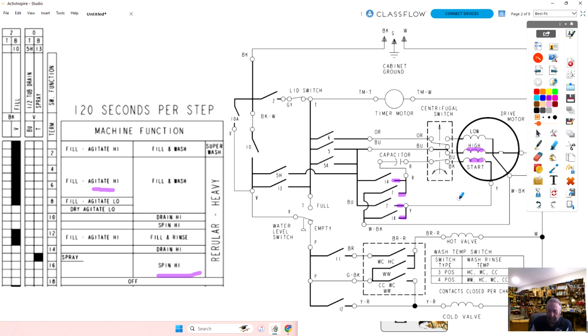What part do you replace? The motor itself? No, no, the timer. Let's do this real quick. It's not advancing. Is that why? No, look, if we want this motor to run, I have to energize the high speed. And I'll just do number 7 again. Here, going up, over, down, and out. And the motor's running. That's the wash cycle.